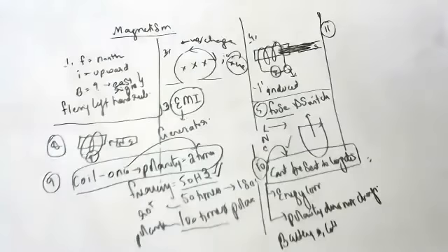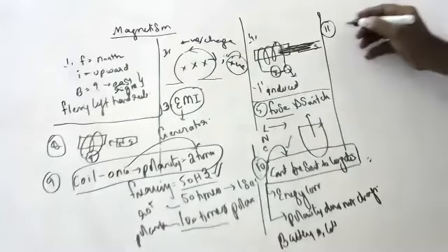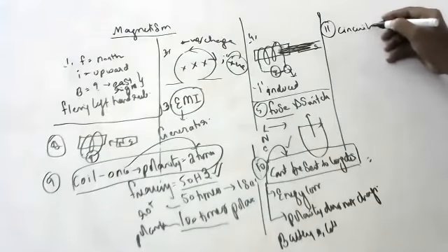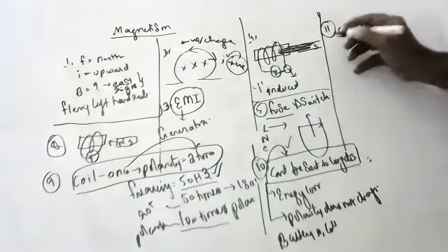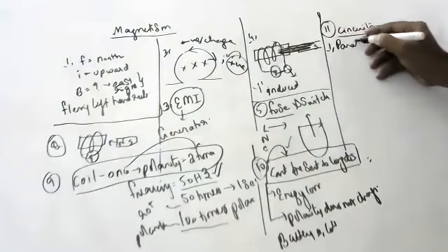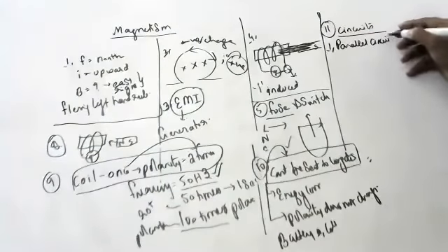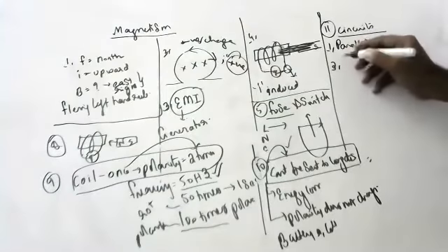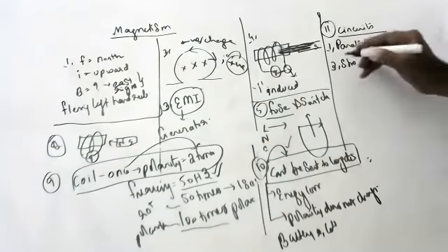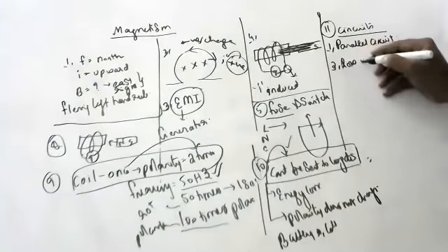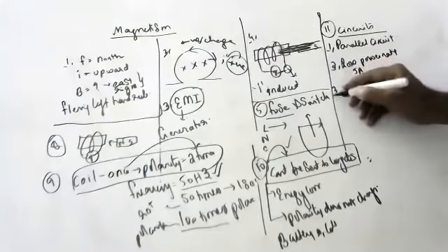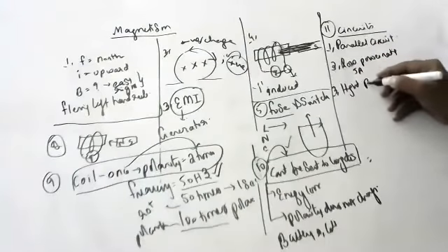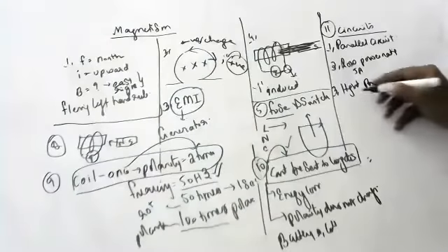Learn the question. List four characteristic features of circuits used in residential buildings. Children, we will use a parallel circuit. Number two, in a parallel circuit, low power rating circuits will be there, which is 5 amperes for bulbs and fans, and high power rating circuits will be there, which is 15 amperes.